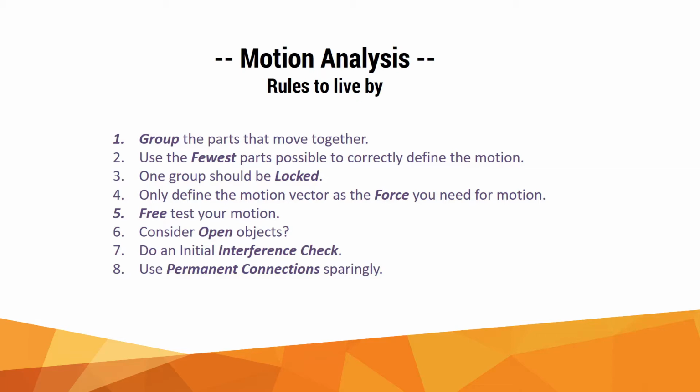The way to use motion analysis effectively is to stick to the basics. First-time users of this function usually overdefine the movement and then have trouble. On the screen is an 8-point checklist. These are the steps and the order in which to do them that will generally guide you through a quick and successful motion analysis. Some of these steps only take a second, but each one is noteworthy.